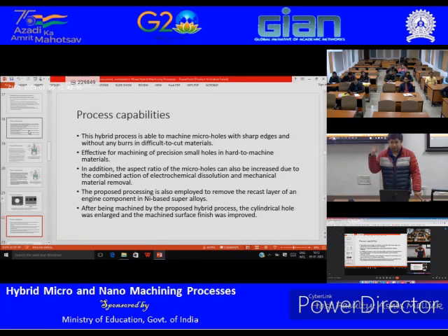So I showed most of the pictures qualitatively, but this is something I learned later. This is one of the suggestions I learned over time, and now I make sure that I try to follow that. Many things can be done qualitatively by showing pictures, but think about how you can present that quantitatively. Maybe surface roughness. Maybe for corner profile, you saw this is a good profile, but what about circularity? You just measure circularity, right?